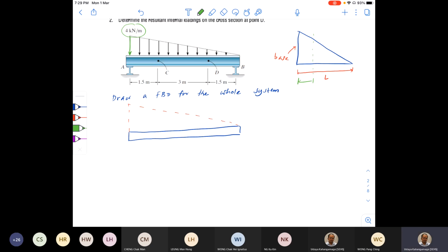So the centroid is located on this line, somewhere here. It's like the center of gravity. In fact, if you take a triangular metal plate like this and try to balance it on your finger, you have to keep your finger 1/3 from the base or 2/3 from the tip. This is the tip. So now this point is actually called the centroid.